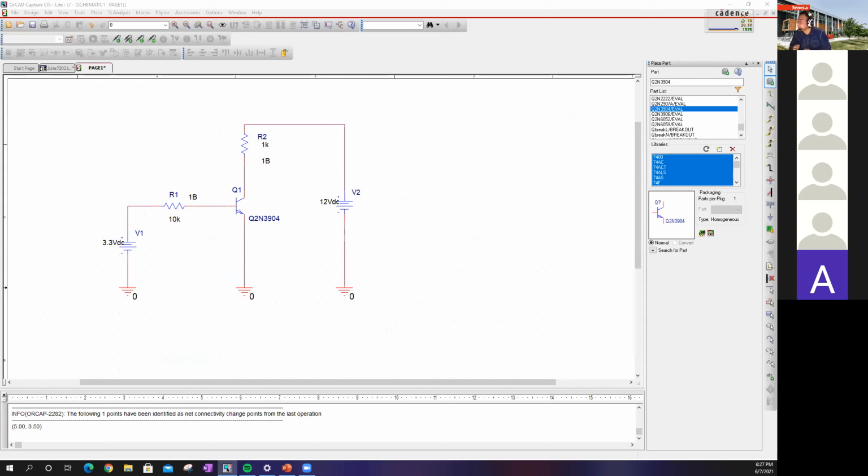You have a question? Yeah, what's up? I want the highest value of the IC to be VCC divided by RL, so we could not have a value above that. Because if we keep increasing the VBB, at some point the IC would get bigger than VCC divided by RL. The IC cannot go beyond that result, which is hard saturation or full saturation.